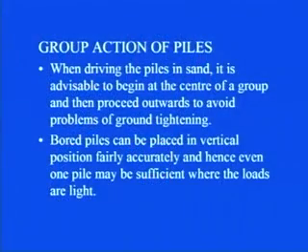However, what happens in the case of bored piles? These piles can be placed in a vertical position fairly accurately, and hence even one pile may be sufficient where the loads are light. In the case of driven piles, you use hammering or vibration techniques to drive the pile, and in that process the pile can move laterally. That can cause the development of eccentricity. However, in the case of bored piles, you create an excavation or a borehole in the soil, and then you do the concreting inside that borehole. When you are making the borehole, the alignment of that borehole is very much under your control. So, in the case of bored piles, vertical installation of the pile is very much possible, and therefore one pile can be used.